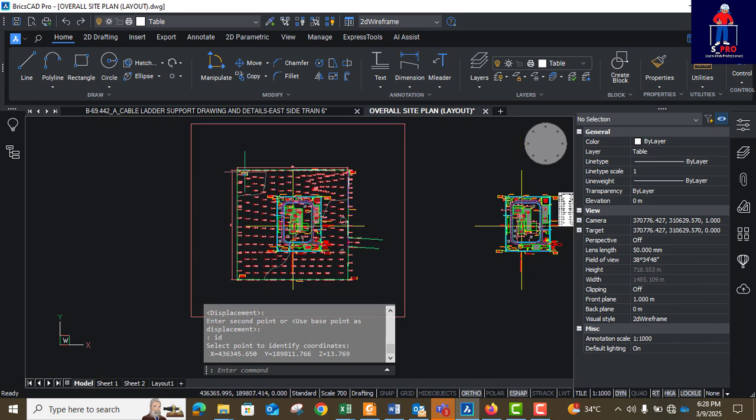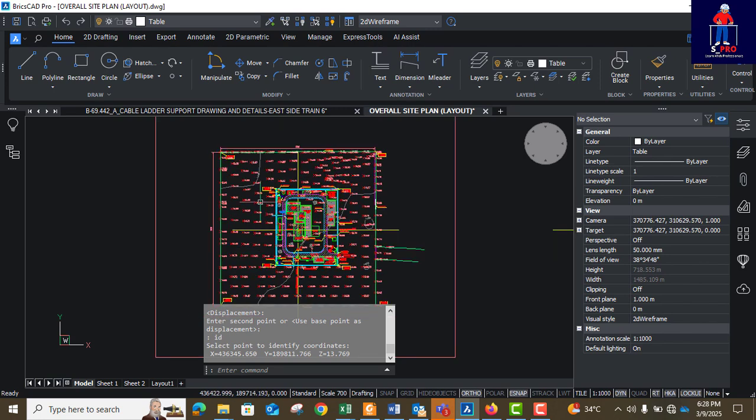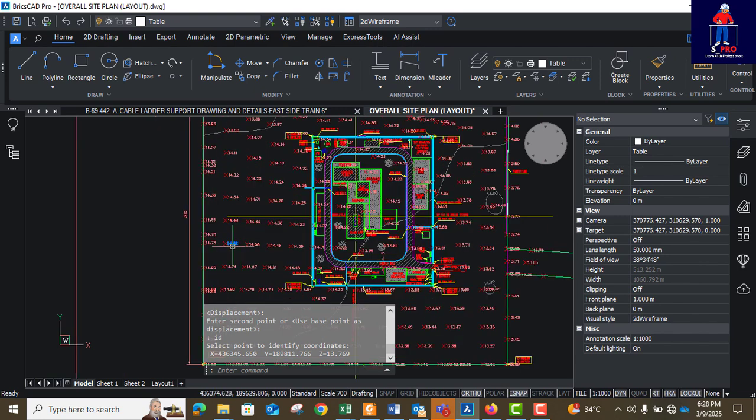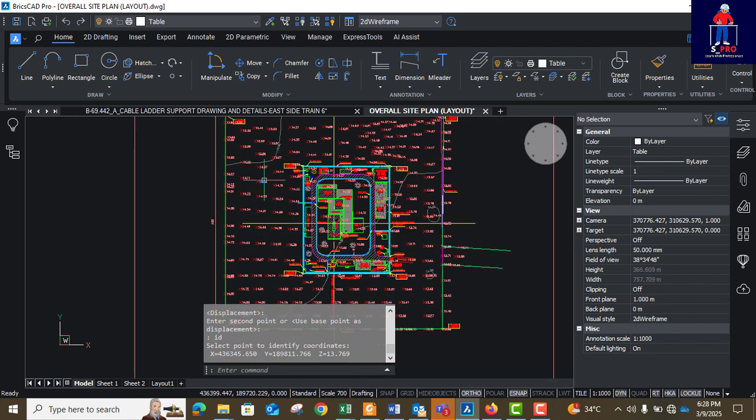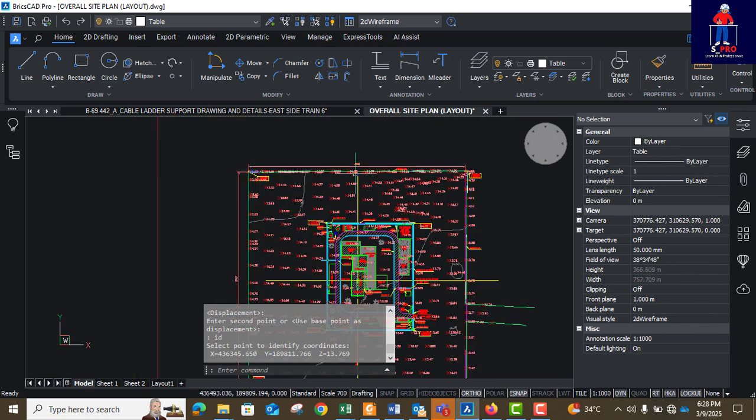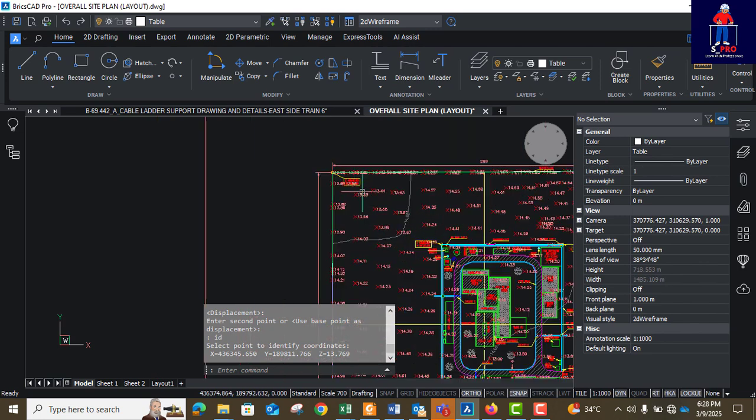After confirming that the coordinates are correct, that's when I moved this topo survey away, because I don't need all these spot heights. It is when we start our site grading plan that we will need the spot height. That one is used to prepare the site and grade it. So that's where this spot height is going to be used. For now, I've confirmed that the coordinates are correct. For you, because I've done this confirmation before, that's why I'm not confirming all that.